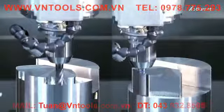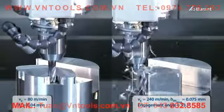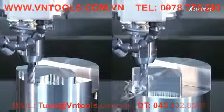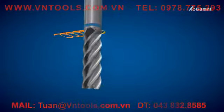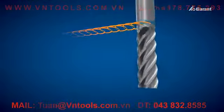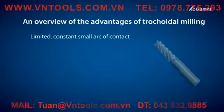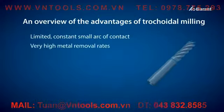The result of this strategy is that high cutting speeds are allowed at full cutting depth, whilst at the same time achieving significantly reduced tool wear. This procedure is achieved by overlaying two opposing movements: straight line and elliptical. This delivers many advantages, such as a limited, constant small arc of contact coupled with very high metal removal rates and very low cutting forces.